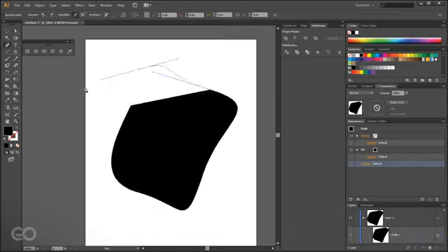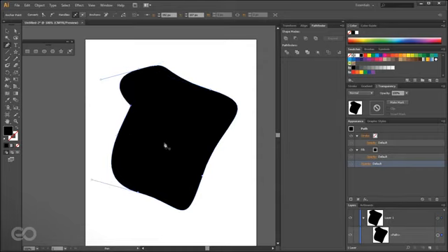So let's say I have this shape, and now I wanted to remove one particular node. By being in the pen tool itself, if I come to any point, you can see that the tool changes. It has a minus sign below it now. By clicking on any node, it deletes the node. It's quite easy. If I go to the path, any position in the path where there is no actual node itself, you can see it gives me a plus sign now. I can go click and it gives me an actual node now. If I want, I can go click and let go, and it has me there.